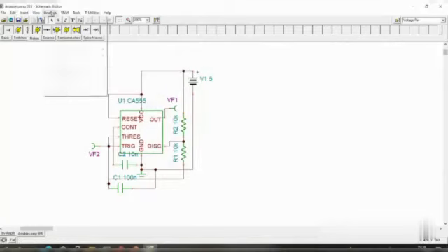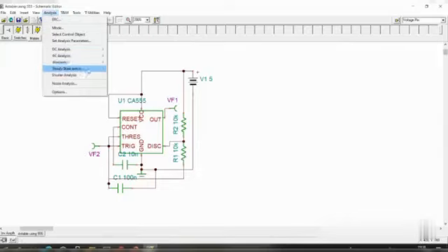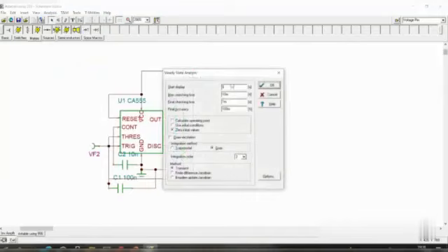And you just go to the analysis, and go to the steady state solver and give this 10 millisecond. I have given 10 millisecond, and this 100, it should be 100%. By default it will show milli, but it should be 100%. So the maximum searching time is 10 millisecond, and the first final checking time is 1 millisecond.